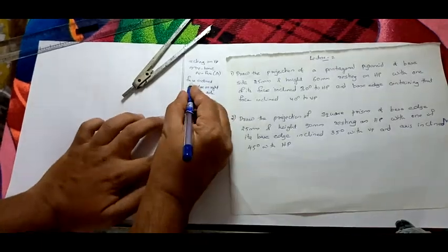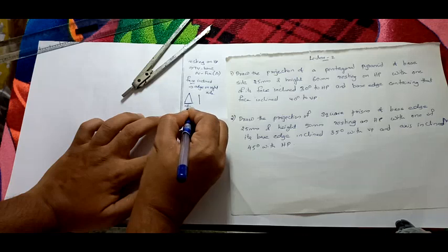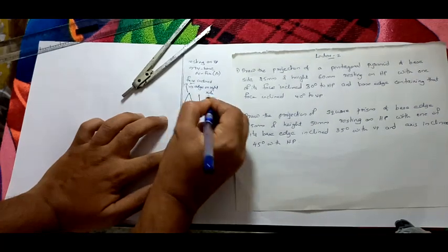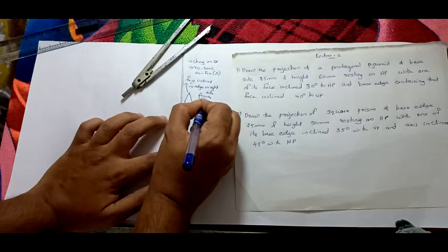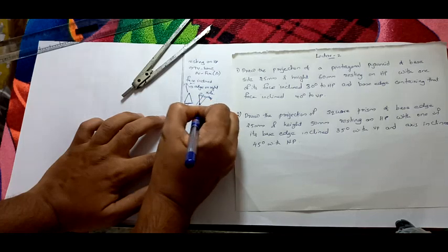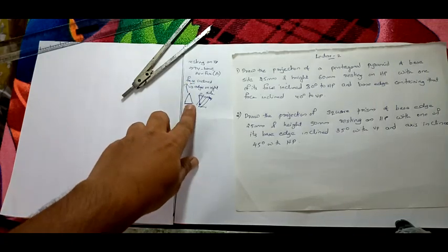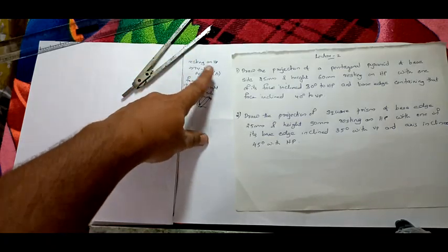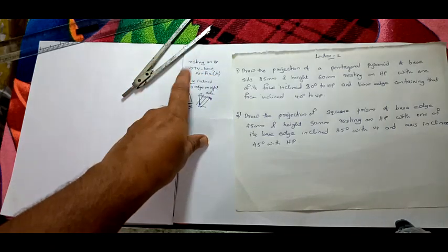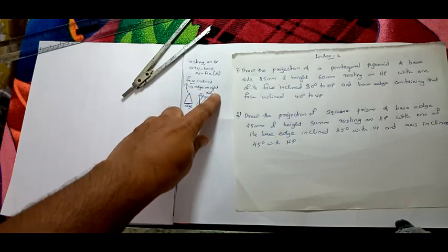So you have to denote it. Face means it's a triangle, and the bottom is an edge. If they had told face edge, that is not related to our question, so I am rubbing it off. Face edge means it's a line, so the bottom is a corner. But here, face means the bottom is an edge, so the right side should be an edge. These two points you have to understand. Resting on HP means the top view is our base, and the face is inclined, so our edge is on the right side.